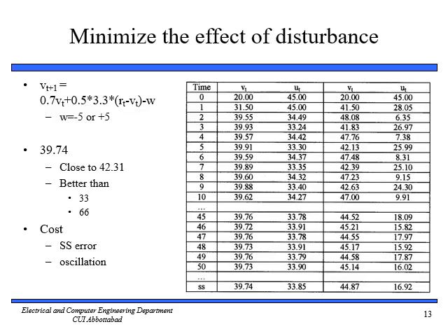In this slide we will talk about minimizing the effect of disturbance. The motivation for using closed loop control was to reduce the speed error caused by disturbances like grade. If you look at the table, this shows the effect of plus 5% and minus 5% disturbance.